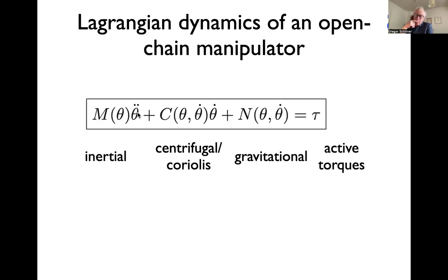That is somewhat of a problem, because then the control action also perturbs other joints and sort of chains down the whole thing. And that's why robots have to be relatively strong to control against that. And the more sophisticated approaches try to anticipate that and already insert the correction before it is experienced. And these are sometimes called modeled torque control. And here I don't go much into that.